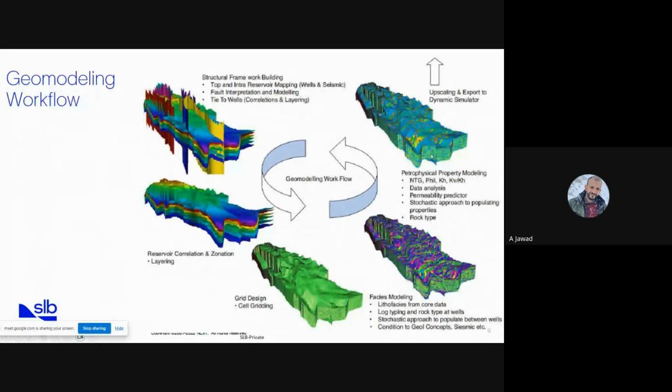After that, we will make the petrophysical property modeling. Maybe I mentioned, sometimes I say petrophysical model, and sometimes I say petrophysical property modeling. This one I mean here in Petrel. When I say petrophysical model only, I mean the model that comes from the petrophysicist, which is basically porosity, saturation, V-shale, net-to-gross. Okay. So after doing the petrophysical property modeling, it is highly recommended that this petrophysical property modeling be guided by my facies.